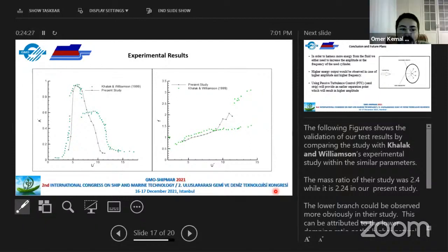So that's very strange behavior of vortex-induced vibrations. But we did not encounter such a thing because our Reynolds number was a bit higher. We still wanted to include this because it gives us a reference. Yeah, sure. Although we're at the end of it, we're still in the TrSL2 flow regime, transition shear layer 2 flow regime. So this is only given as a reference.